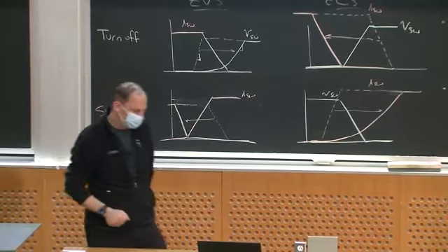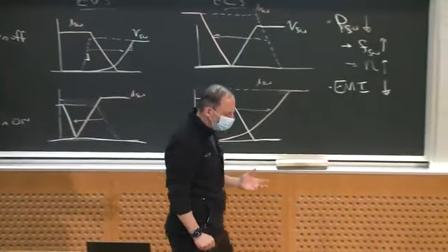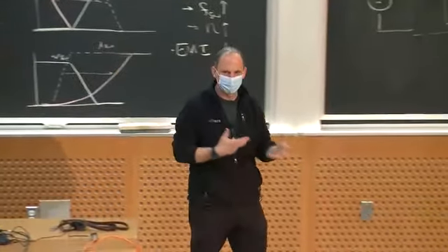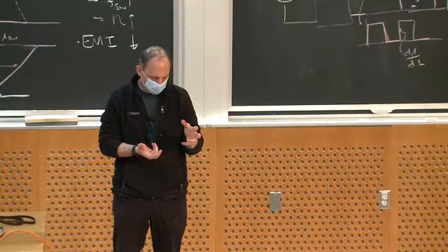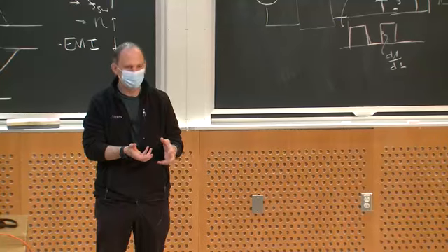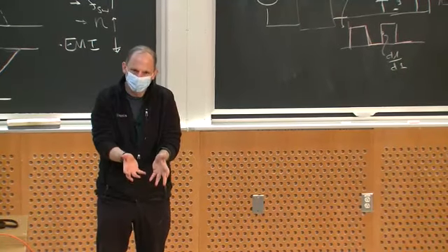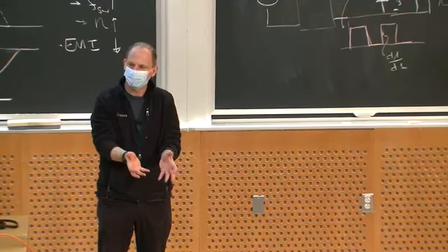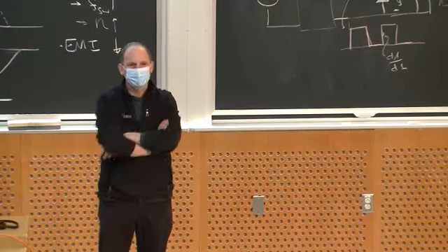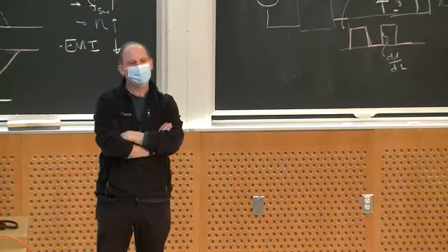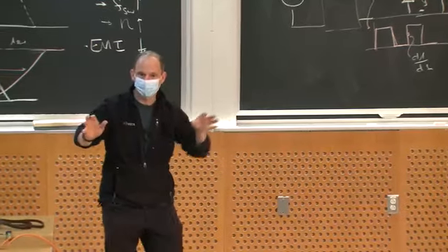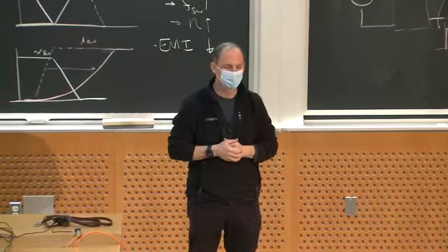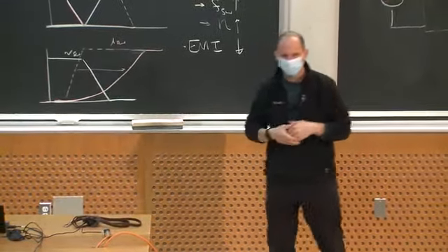Another category of circuits is, geez, I don't want to redesign and conceive this whole funny operation of the circuit in order to achieve soft switching. What I'd like to do is more or less design a PWM converter like we've been talking about all semester, and somehow add in some auxiliary circuit that's going to help me get soft switching. Both of those strategies are used, and I'm going to show you one of each today.